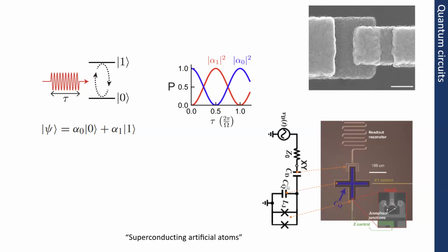Then these junctions couple to this big capacitor, and altogether the capacitor and the junction create a resonator, which is a nonlinear resonator, and this nonlinear resonator is used as a qubit in this case. Then we couple this system through the coupling resonator over here, and this is how we can control the state of a quantum system, a quantum resonator, a microwave qubit.